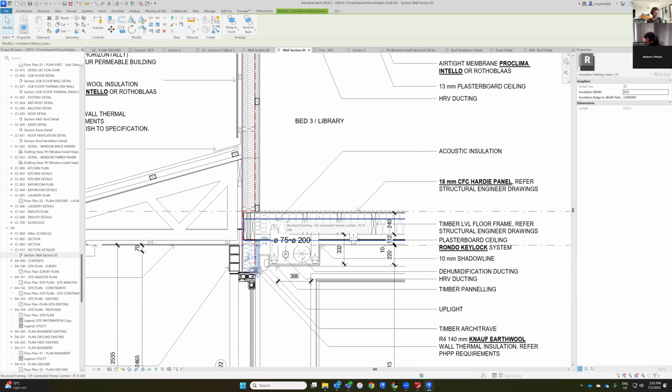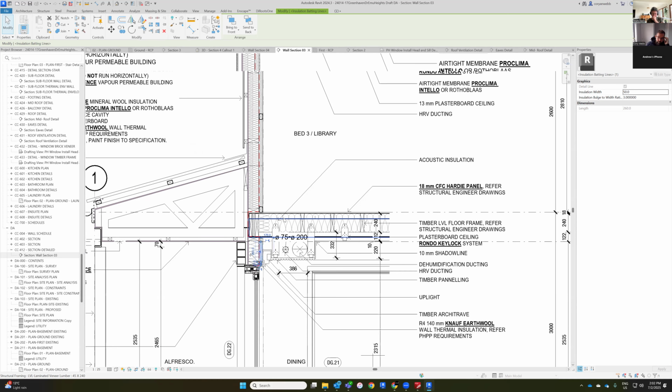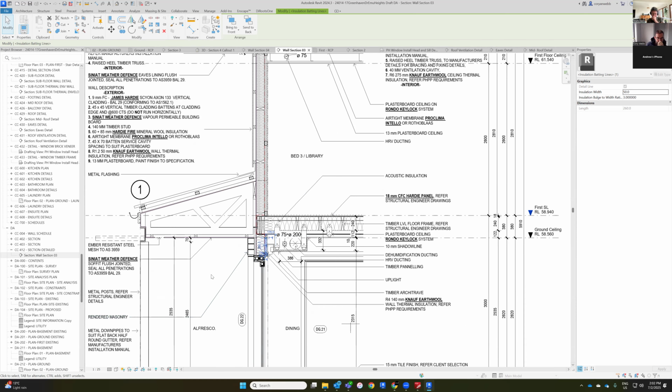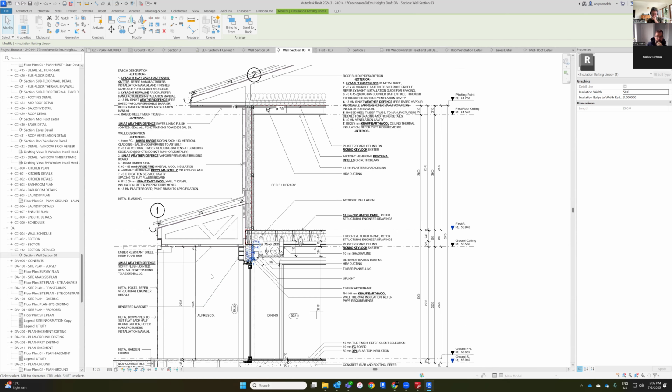I'll have a chat to Scott. Separation of dehum. Do you happen to know, Mark, how far they need to be separated? No. I would say 70, maybe 100. No, wouldn't even be that. Wouldn't it? But it'd be 50 as a minimum. Yeah. It's standard practice to do that because of the bell mouths on the duct if you're going to have longer runs on it. Okay.